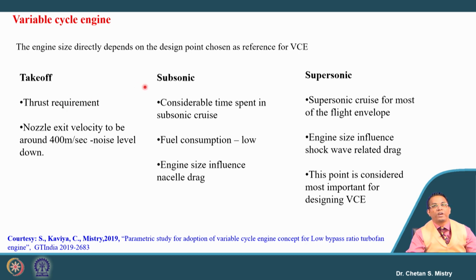Suppose we are looking for subsonic operation. Most of the time we operate our aircraft under subsonic conditions, or run our engine under subsonic cruise condition, where we consider more the fuel economy, or we want to reduce the fuel consumption. Under that configuration, the engine size influences the nacelle drag. So we need a configuration focusing on fuel economy. We can say our turbofan engine acts fine under this configuration.